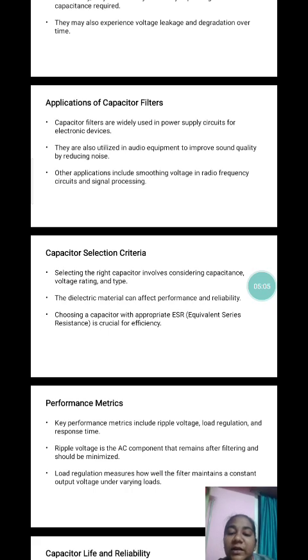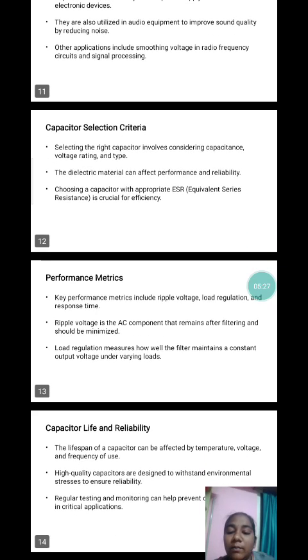Capacitor selection criteria. Selecting the right capacitor involves considering capacitance, voltage rating, and type. The dielectric material can affect performance and reliability. Choosing a capacitor with appropriate ESR, equivalent series resistance, is crucial for efficiency.